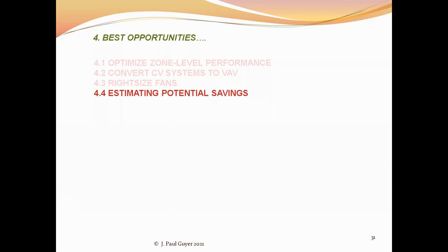Secondly, the fan can be diagnosed by a static pressure adjustment, but this is only on an older VAV system. Reducing the static pressure in a VAV system reduces the fan horsepower consumption. So by gradually reducing the static pressure set point to a level low enough to keep occupants comfortable, fan speed will be reduced, thereby reducing energy consumption.